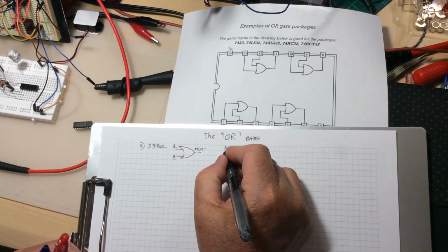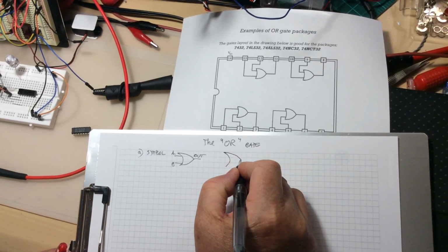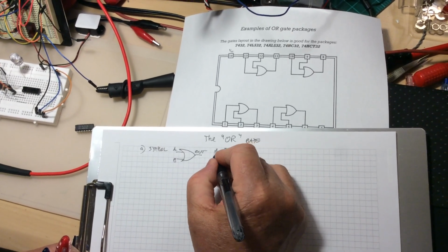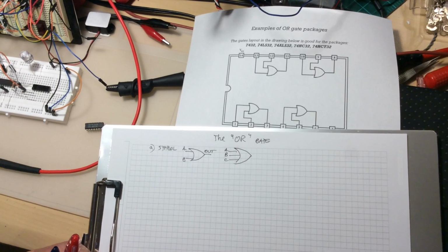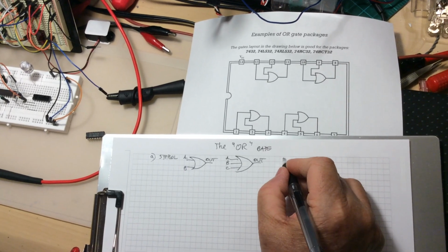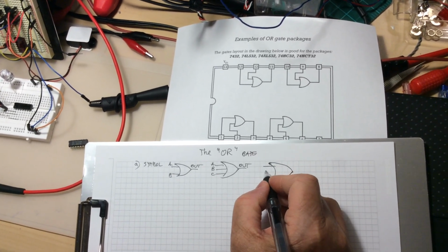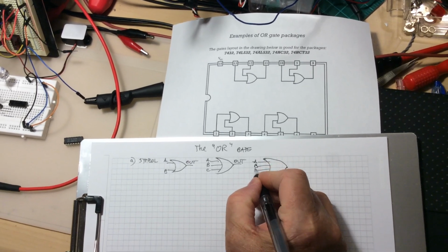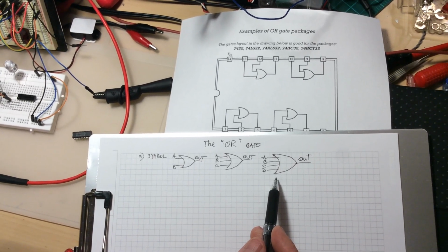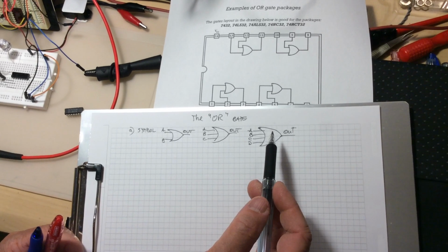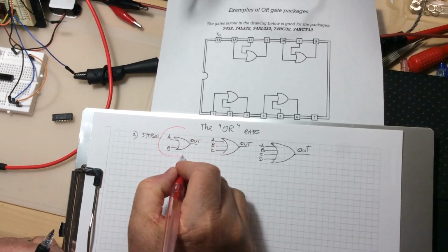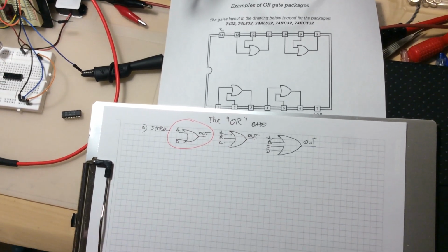Just for you to know, you may have other gates bigger than that. The symbol is going to be the same, but they may have 1, 2, 3 inputs. So if it is the case, you are going to give them letters, something like that, and here is going to be the output. And the same principle applies if you have a bigger gate, like this, having 1, 2, 3, 4 inputs, A, B, C, D, and the output is here. And you may have other similar ones with more than 4 inputs, like 8. For the purpose of simplifying, we're going to start using a simple one with only 2 inputs.